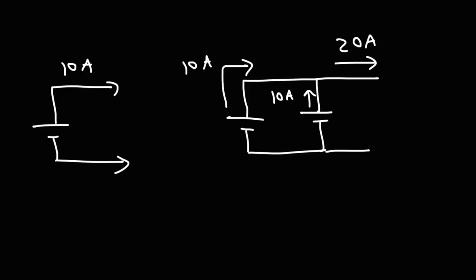If you want to increase the voltage of multiple power sources, you want to connect them in series with the positive terminal of one power source to the negative terminal of the other DC power source.